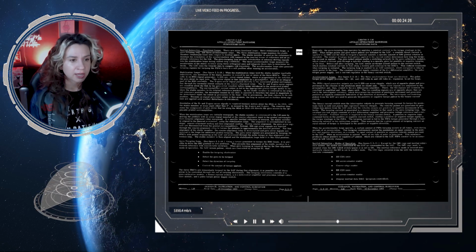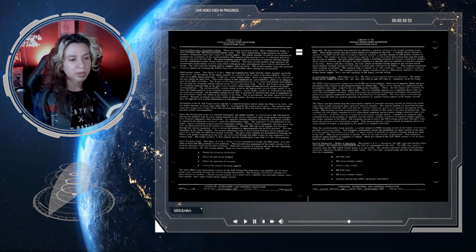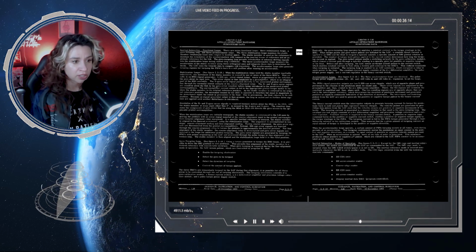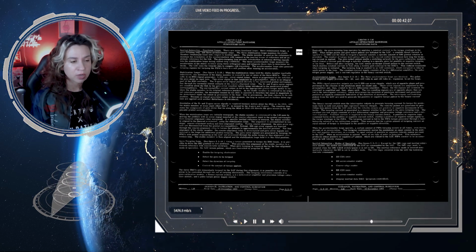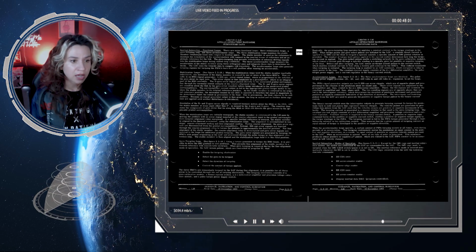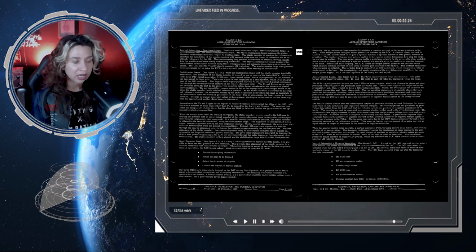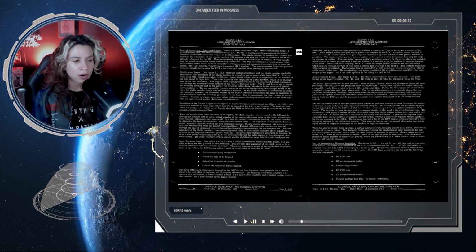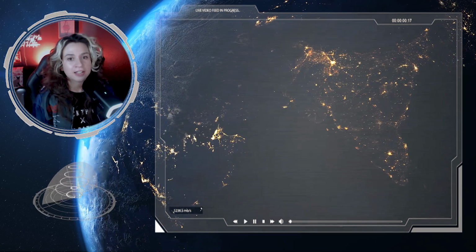Except for the IMU cage, the inertial reference modes, the modes that are controlled by the CDU, are commanded by the LGC. The IMU cage mode is initiated when the IMU cage switch on panel 1 is set to on. The inertial reference mode is entered automatically whenever the ISS is not in another mode. The CDU logic receives from the LGC the following discrete commands: the ISS CDU zero, the ISS error counter enable, the coarse align enable, the RR CDU zero, the RR error counter enable, and the display inertial data, or DID.